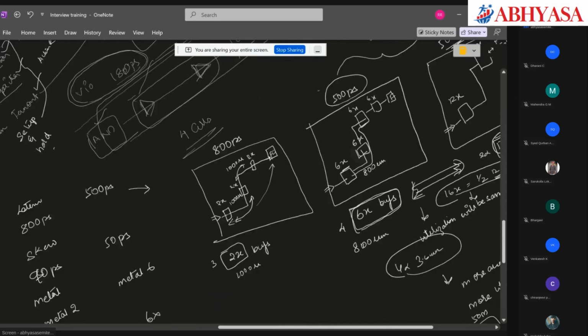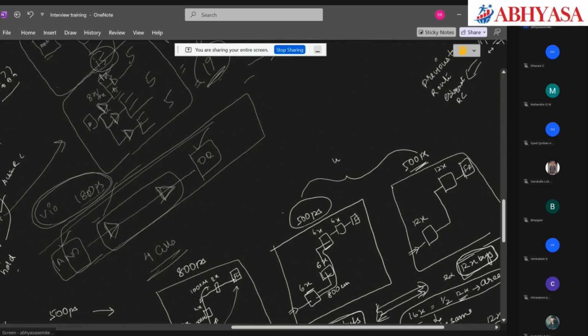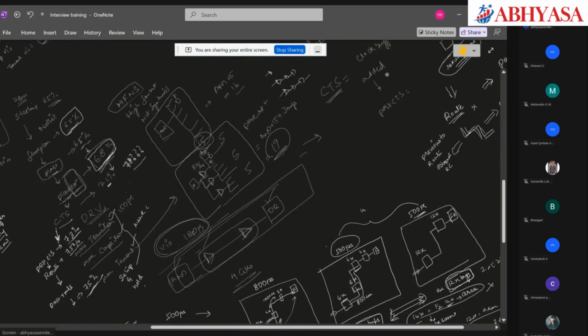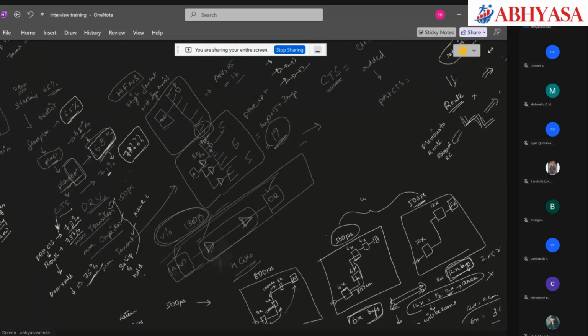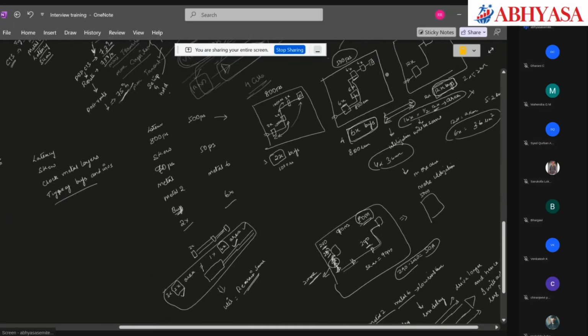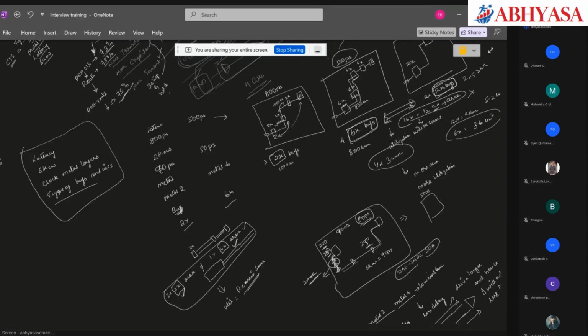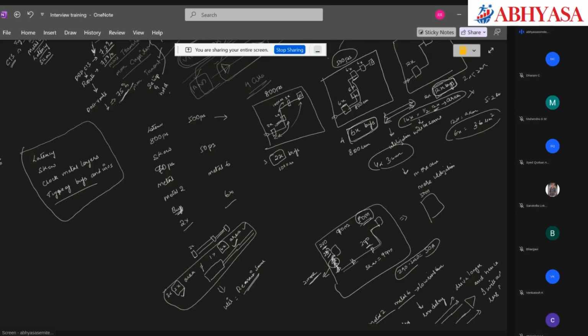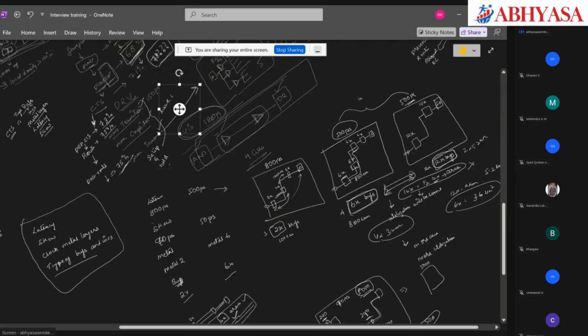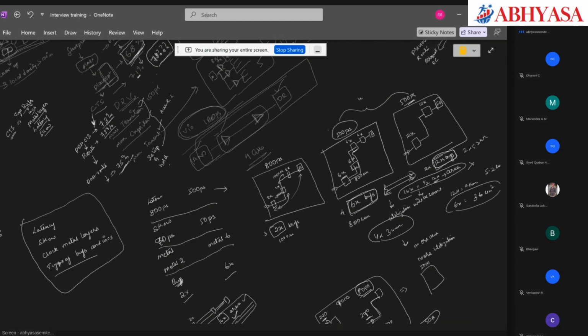So now we were talking about sudden utilization jump between place opt and CTS. So while doing clock tree synthesis, all these factors mentioned here will affect how many buffers I will add or how much area, gate area I will add to my design, right? So these should be carefully chosen. These values, either the skew, latency, or the metal layers that we are using for CTS, or the buffer drive strength that we are choosing, these should be very carefully chosen to reduce the amount of area we are adding to the design.